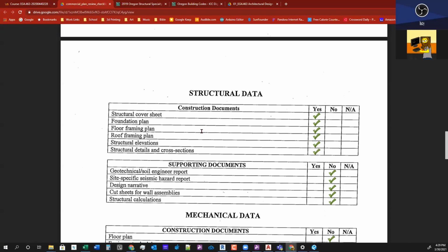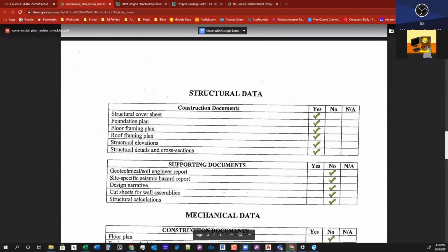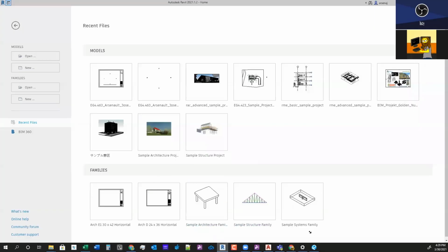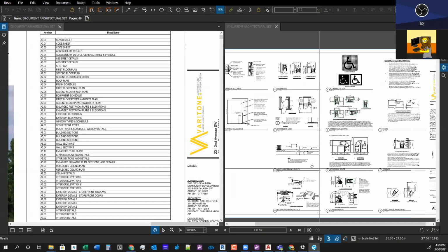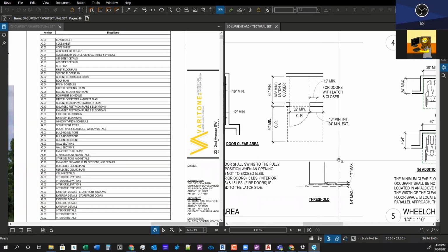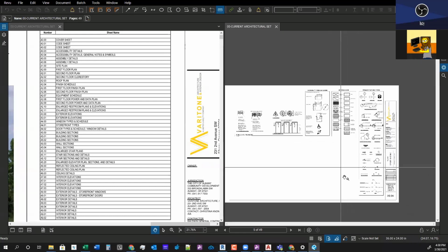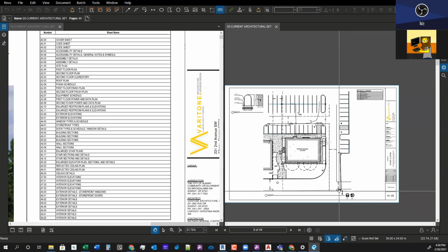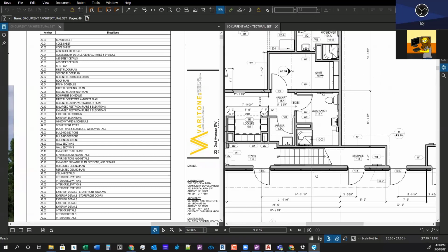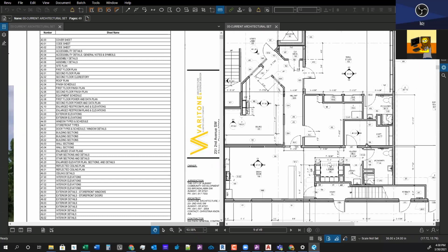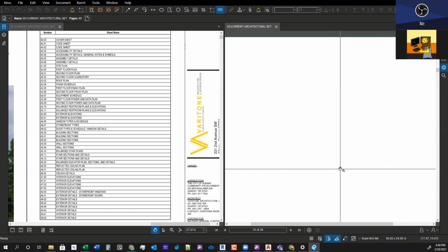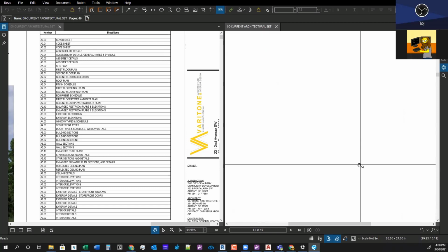And I can also show you how most architects in their models will have a dashed line representing that clearance space. So if we were to look at, let's see, this dashed line, often they'll have those on their doors anyway, and I'll show you how to add those into our door families. We could probably find one that's already made. It doesn't look like they have any of the door clearances on here, which isn't required. Most of the time that's just to help